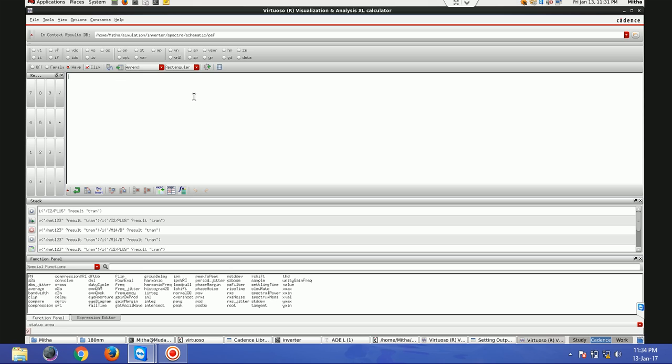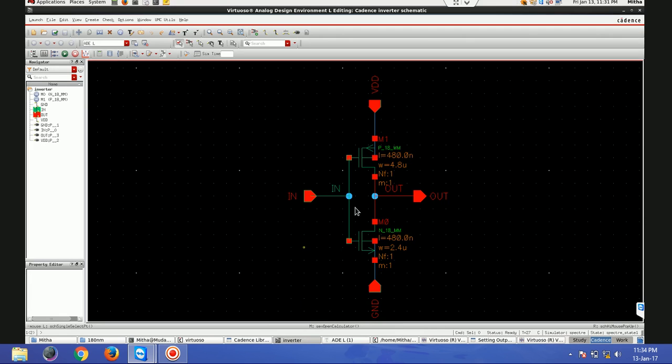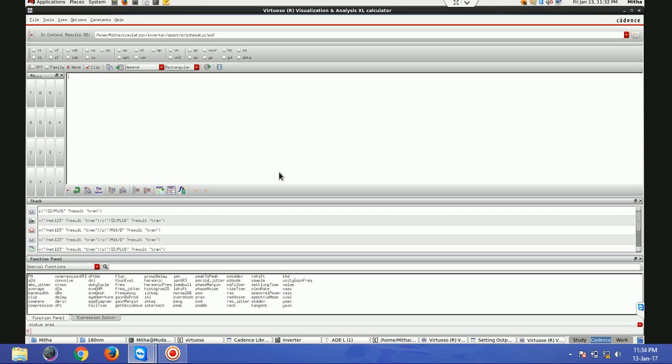Okay. Now here, when you are doing transient analysis, you have to choose VT. It's for voltage, VT. For example, in my circuit, I want to write one expression for this Vout. So if I'm doing transient simulation, I will take VT, and similarly for current it is IT. This is for AC simulation when we are checking some AC response, and this is VF, and similarly this is for VDC, and this is for DC simulations.